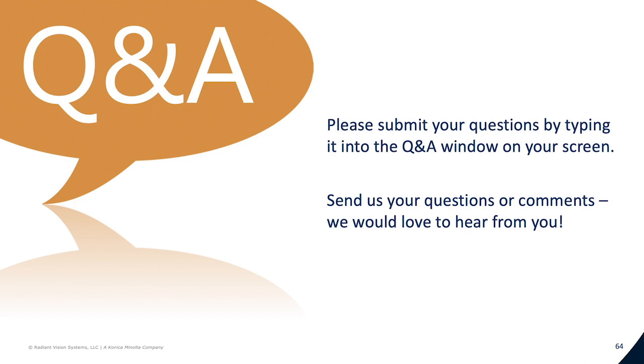And we have a third question from the audience, which asks, what's the brightest image that can actually be captured in a production measurement system? Well, that's a great question. We actually use high dynamic range imaging solutions that are based upon a technology called electronic bracketing. That allows us to expand our fundamental measurement range through sets of composited exposure times. And on top of that, we can also extend the measurement range to even greater than 1 million candela per meter squared by applying the right neutral density filter in front of the sensor.